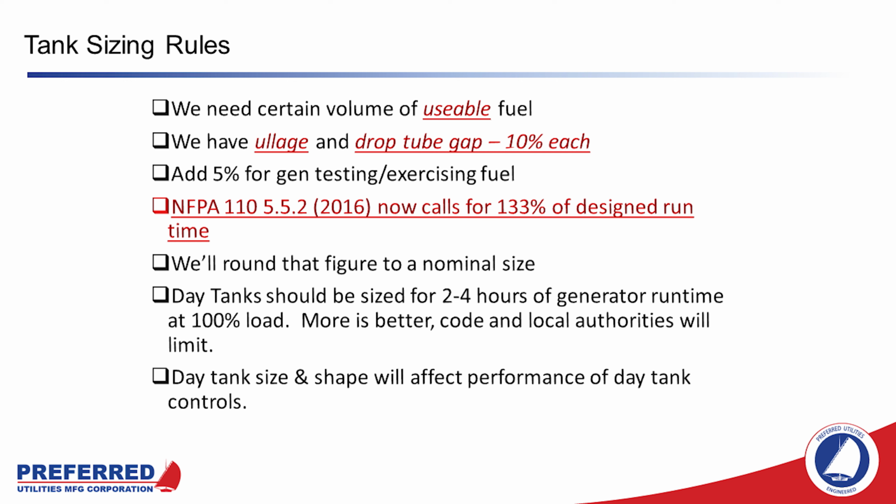Also, NFPA 110 requires that you carry 133% of the fuel for your designated runtime. So they sort of require a 33% safety factor. And then finally, when you have day tanks, the amount of fuel in your day tanks is usable fuel. So that can be added to the amount of fuel in your main storage tanks.